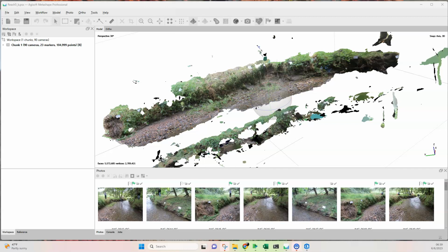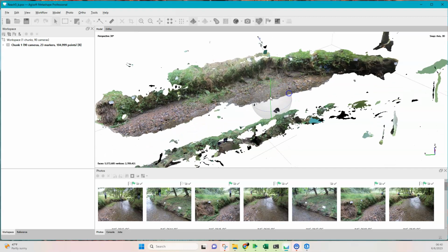I then also give you, and it's in a folder called Elevation in the Lab3 data file, a DEM, digital elevation model, produced by the federal government, which shows elevation throughout the region. You have to download these one small tile at a time, so it's a good chunk of campus. And we're going to imagine putting that DEM right on top of this and doing exactly what we did with the string. Imagine taking a line across this grid showing us elevation and just teasing out the elevations of each square. We're going to do the same thing with a grid we make from our 3D model.